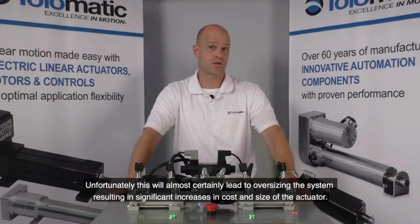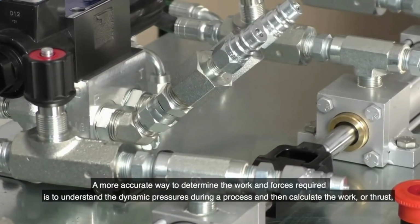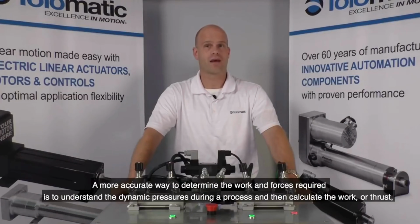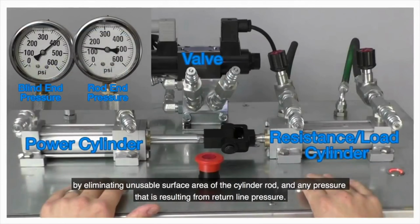Unfortunately, this will almost certainly lead to oversizing the system, resulting in significant increases in cost and size of the actuator. A more accurate way to determine the work and forces required is to understand the dynamic pressures during a process and then calculate the work, or thrust, by eliminating usable surface area of the cylinder rod and any pressure that is resulting from return line pressure.